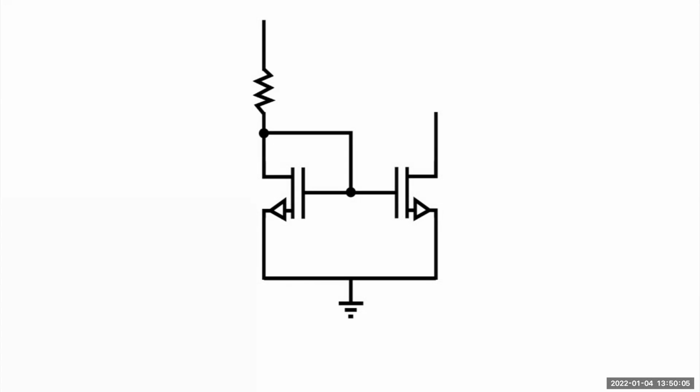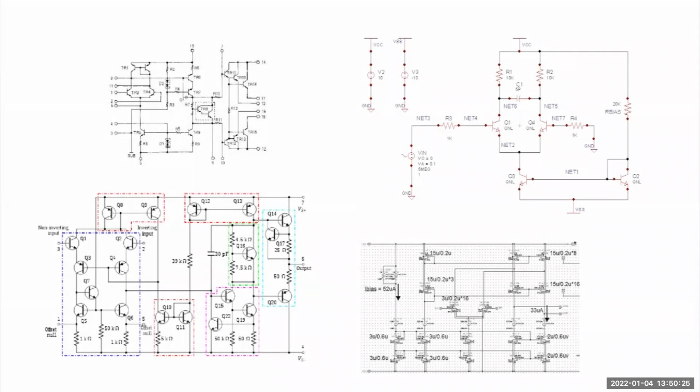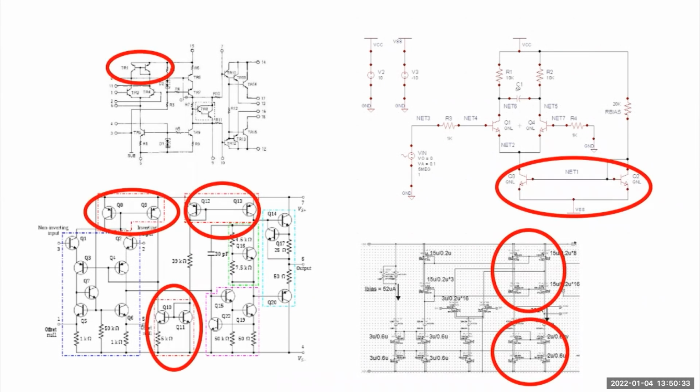Of course, for a current mirror to function, it needs a reference current. This is set by attaching an appropriate size resistor to the collector or drain of the reference transistor. As we mentioned at the beginning, current mirrors are essential in integrated circuit design when a constant current is required regardless of voltage. We also see the circuit heavily utilized as a constant load in differential pair amplifiers. There are many variations of current source circuits that optimize the behavior for certain applications, but we have seen the most basic designs and how they function.